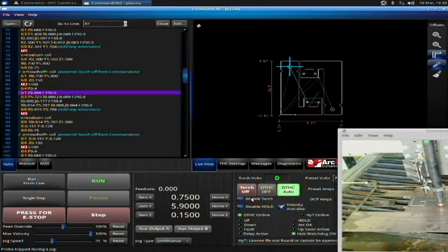When you have a misfire, your first step is to simply hit the stop button. Your second step is to figure out why the plasma did not fire. So you want to look at your plasma and see if there is an error code on the front. Go through your plasma cutter's manual and understand what the error codes mean. It's very important that you don't just assume, oh, well, something's not working right. You want to understand why it didn't cut, because there is a reason.